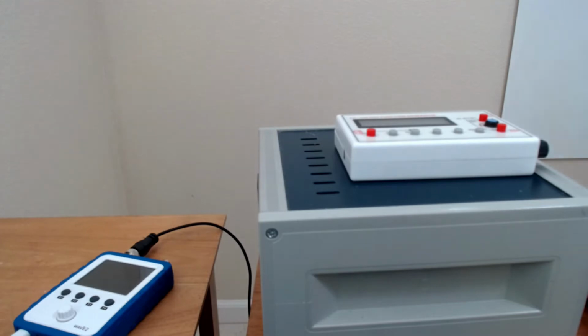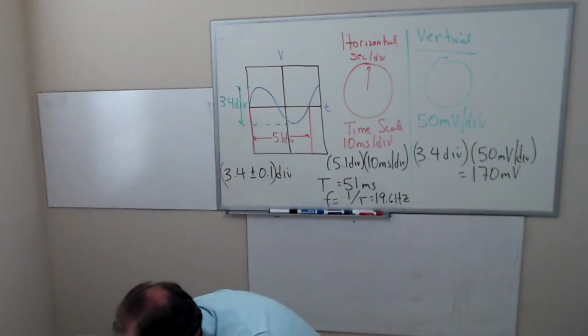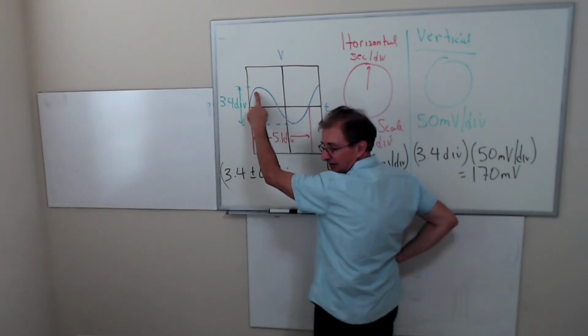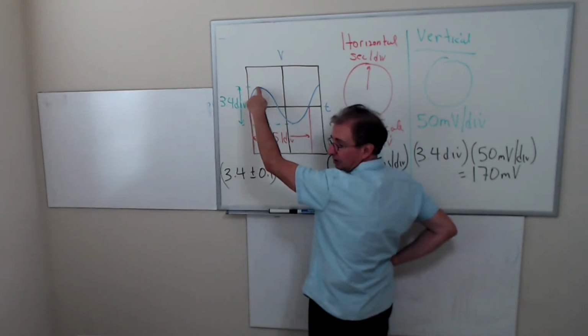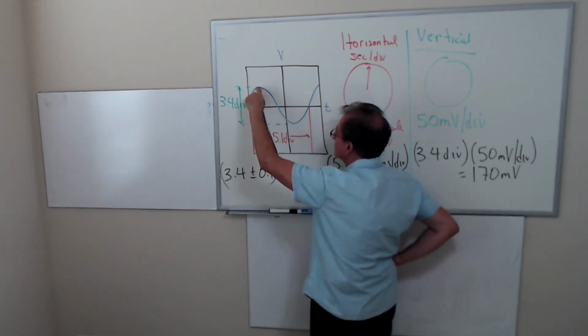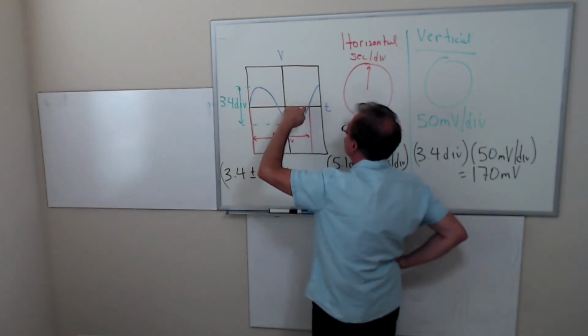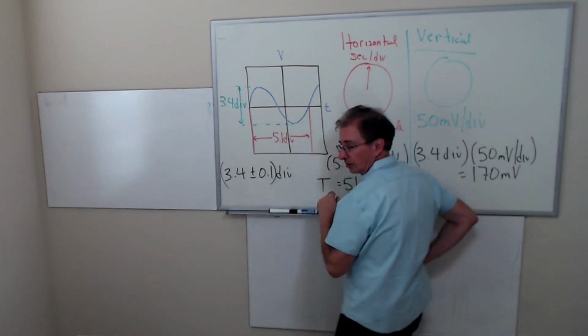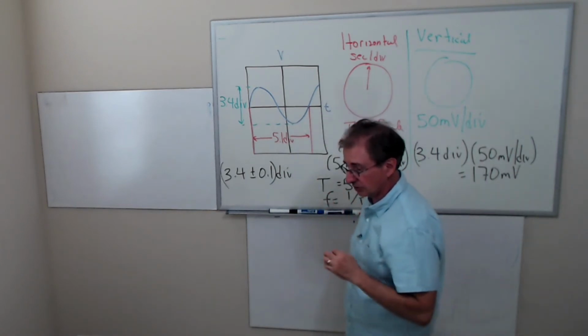You can tell the scope when you want it to start measuring the signal. You want it to measure here when the signal is going down, or you want to measure here when the signal is going up. Let's call it triggering.